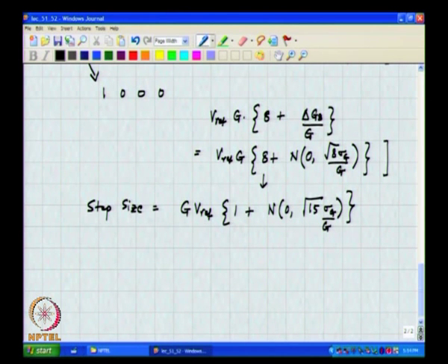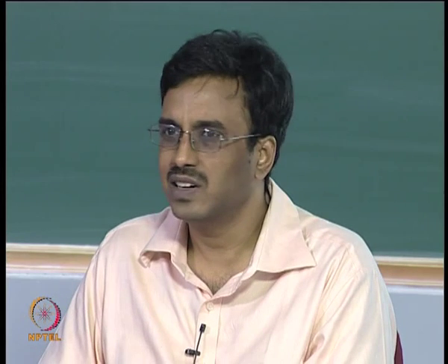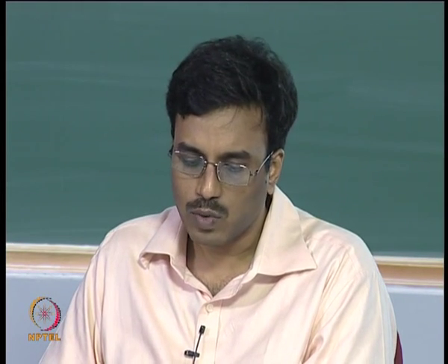All right. So, this is telling you that the step size at the major code transition will have a variance which is not just dependent on the matching, but it is matching the variance of the individual element multiplied by the number of elements that are there, which is basically roughly 2 to the n, okay, or the standard deviation is sigma g by g normalized to the LSB times square root of 2 power n minus 1, for a large n it is roughly 2 power n, okay, all right. So, why do you think this result makes sense?